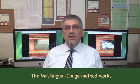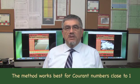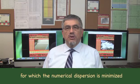The Muskingum-Cunge method works by matching physical diffusion with numerical diffusion. The method works best for Courant numbers close to 1, for which the numerical dispersion is minimized.